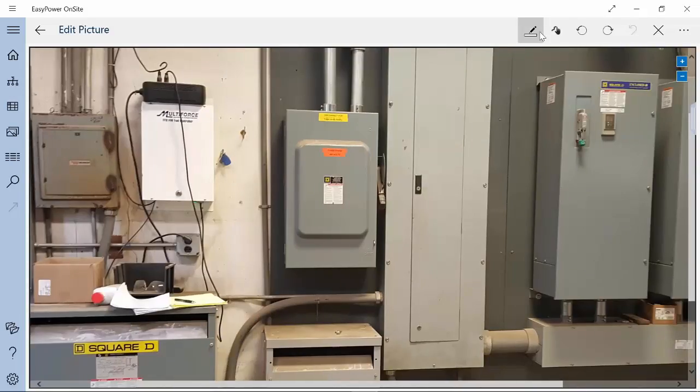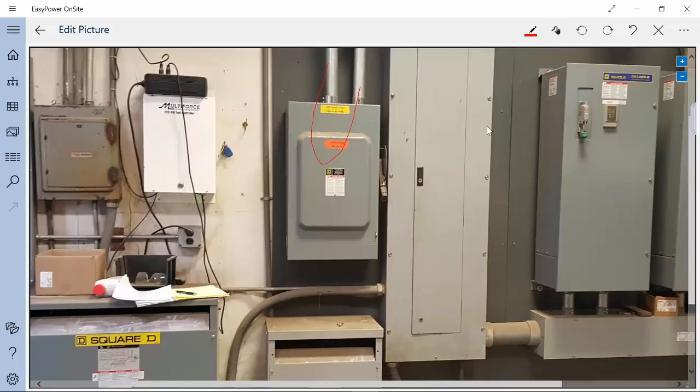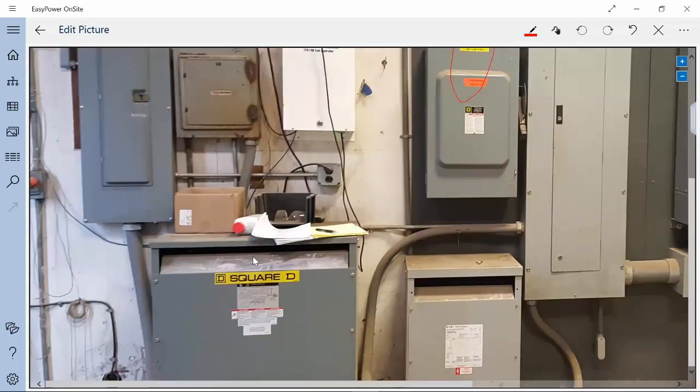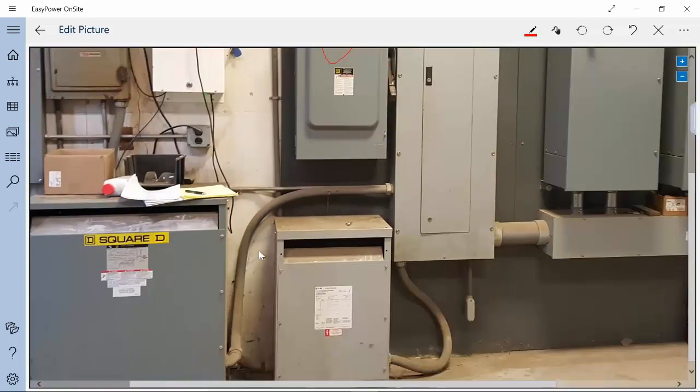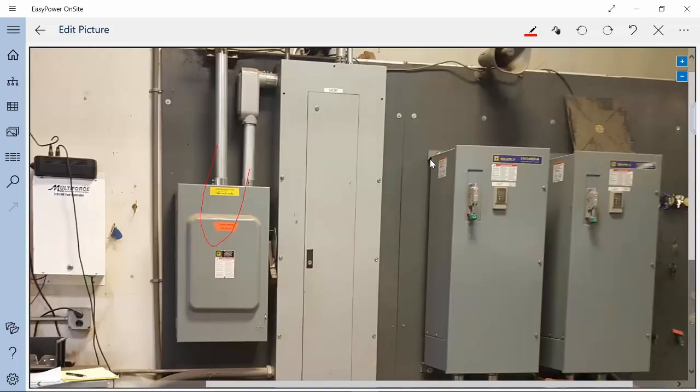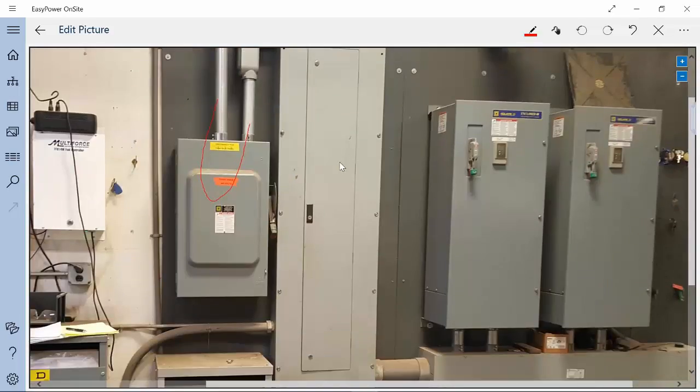All right, so we're looking at the picture as I look at the project. I'm seeing the main current come in through the main power, come in from the utility, go back to my MDP, which is this panel on the right. I see that it has loads that go out to the reduced voltage or step-down transformer. There's a Square D and an Eaton transformer, both of which go to panels. For the purpose of this demonstration, I'm going to map out how to do an outboarded transformer, and then I have some number of motors, presumably that go to these starters, and I'll see on the schedule that I have other motor loads. So this gives me a clue on how I want to take my one-line diagram.